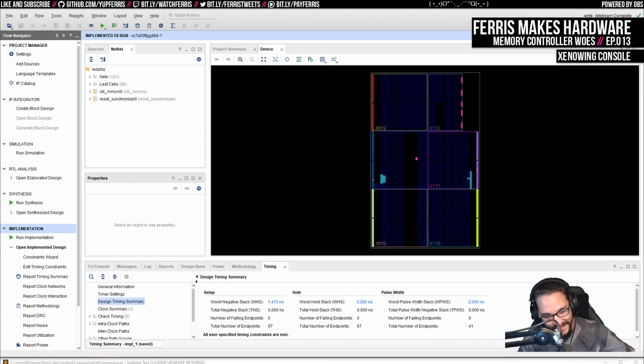I went through my registry and deleted all the keys that I could find that were related to the old version. That didn't help. I was a little bit lucky, though, because I still have a Quartus install on my laptop as well. And that actually worked in order to regenerate the IP, so I could at least do some iterations on changing parameters in it. And with a certain configuration with really bad performance, I did actually get it to meet timing just on its own. As soon as I added my own test, it would stop meeting timing again, which was really annoying. But it also, again, would give pretty bad performance for the controller itself.